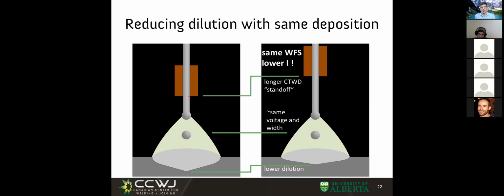Sometimes you can get away with a sinusoidal waveform in subarc welding, just because the arc is so massive that it takes longer to extinguish. Still, I do not advise that. But you can buy a machine that gives you a square waveform. You'll be paying a pretty penny for that machine. Sometimes it's good. Sometimes, based on your knowledge, you say, hey, let's do this solution for free that is more or less the same. Pretty cool. All right. So